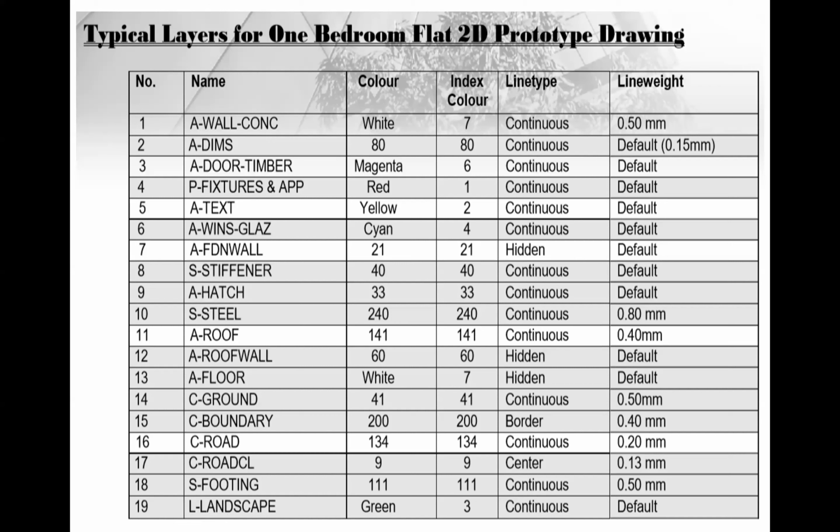For those persons who didn't want to buy it, they would sharpen their pencil and draw, and by the time they make a couple strokes, the line type starts to change in weight and they sharpen again, and you have this inconsistent line type, and your lecturer would have been marking down for line weight and say, boy, they're not consistent. Well, we don't have that problem here. All we need to do is decide what line weight we want for the layer, and anytime that layer is being used, the line weight will always be the same, so it will be consistent.